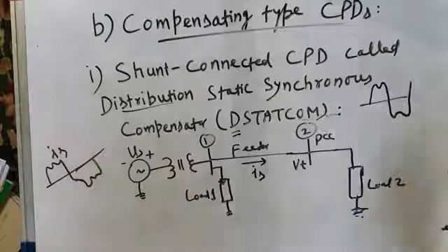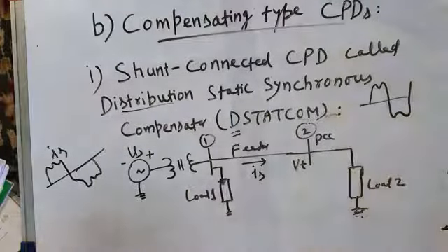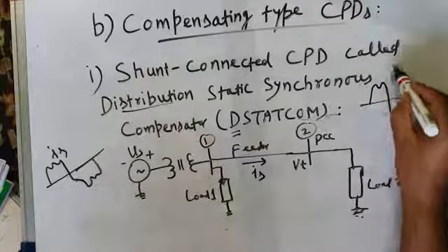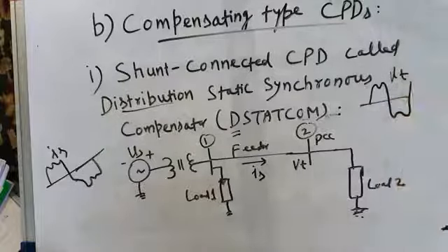And if it is a three-phase induction motor, a heavy, large three-phase induction motor used there, then since this induction motor is fed from distorted voltage, Vt is distorted. Because of this distorted current, the performance of the induction motor will deteriorate. It will produce more heating, more losses, less efficiency, cogging, torque pulsations, vibrations, noise, and so on. We have discussed it in the previous lecture.